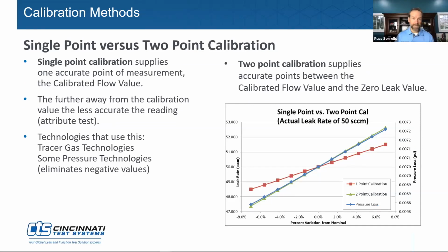What I always used to say is dunk the part underwater, get a graduated meter, fill the graduated tube up with water, and then put it over the leak and time it. That's what I always used to tell customers. Then you know exactly how much flow. That's back in the olden days. And interestingly enough, that's actual flow because you're flowing into atmospheric pressure at the time you're testing.